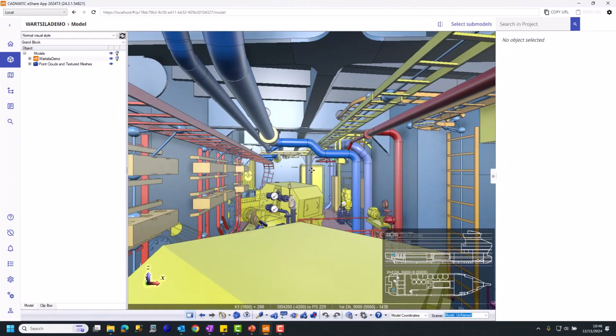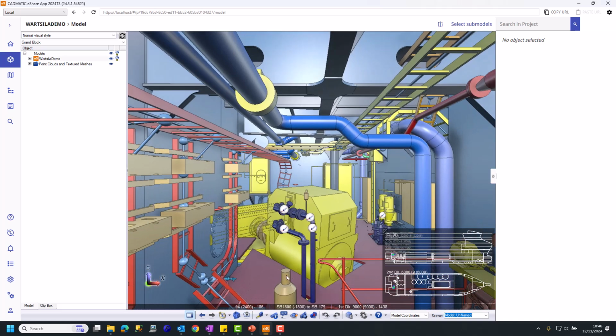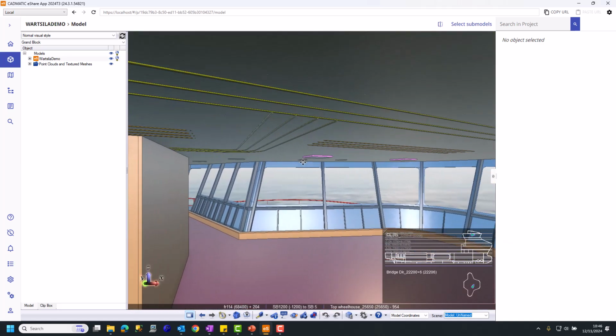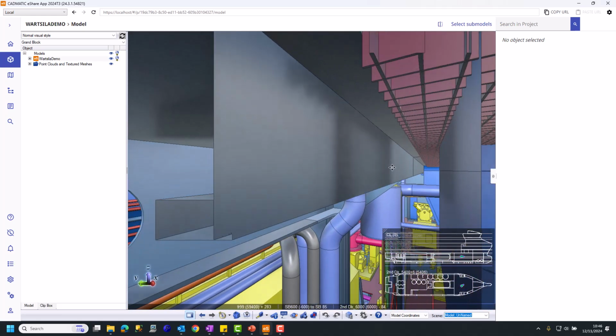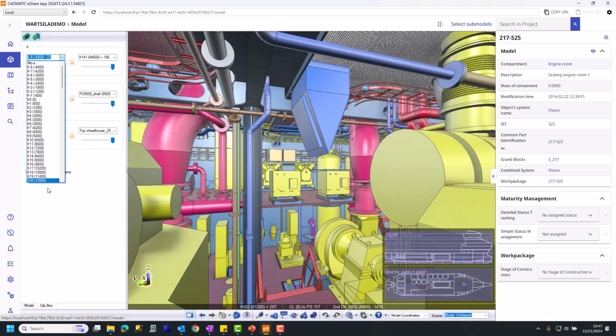If we take a look inside a typical Cadmatic model, we can see that the coordinate system shows frames positions and we have a coordinate map in the bottom right of the window. These both help us understand where we are positioned in the project. Indeed, if we click on the coordinate view, the camera position moves to that location. Furthermore, when we look to clip the model, we have access to all the reference positions in the project.